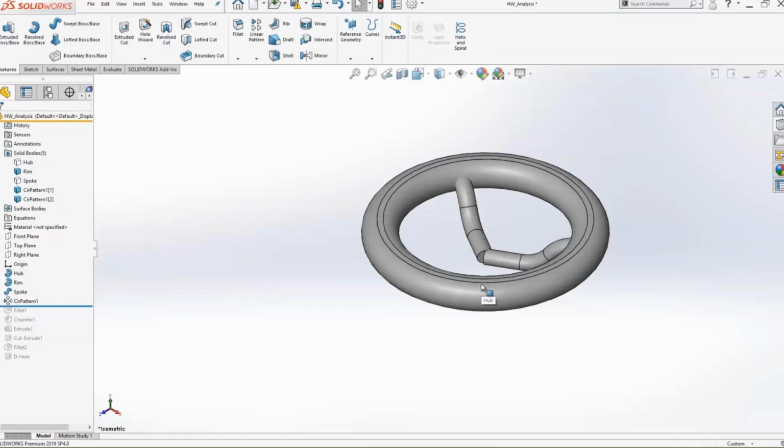You can hold those combinations down as well, just a little side note. So if you hold down the Tab key and simply start dragging your mouse around, it'll actively hide things. Kind of interesting, but it's all about Tab to hide, Shift-Tab to show.